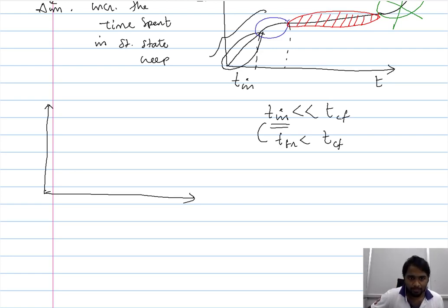So generally, the curve is represented in this manner. When you compare the creep rate in this zone, and this zone, and finally this zone, the creep rate in this steady state zone is significantly reduced. But there is still some amount of strain that is experienced by the material in the steady state creep.